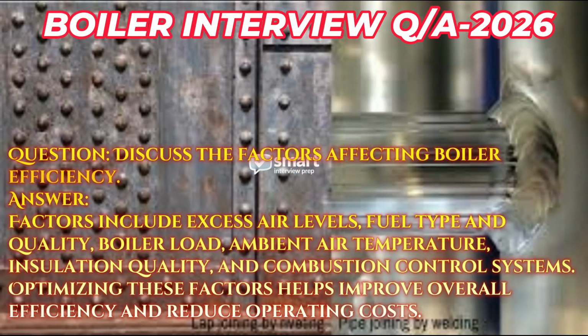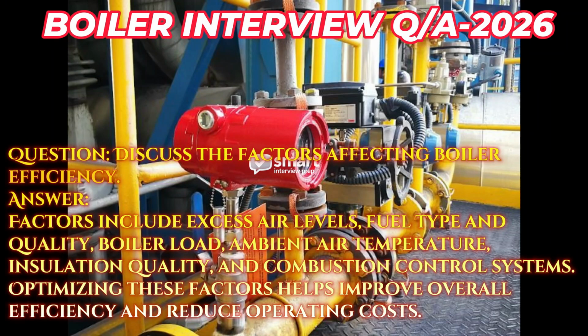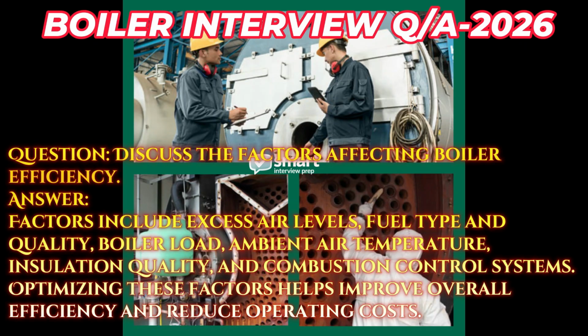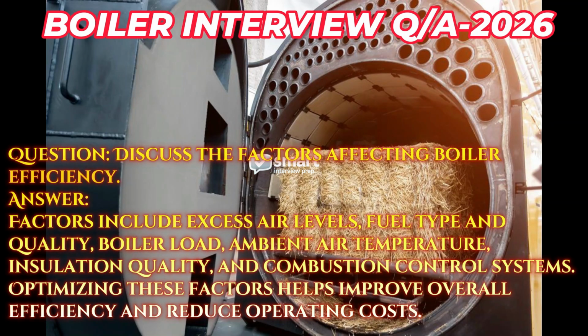Question. Discuss the factors affecting boiler efficiency. Answer. Factors include excess air levels, fuel type and quality, boiler load, ambient air temperature, insulation quality, and combustion control systems. Optimizing these factors helps improve overall efficiency and reduce operating costs.